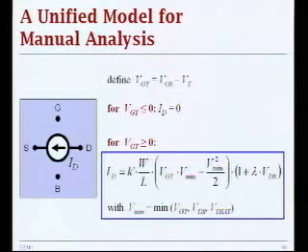People sometimes use the alpha power law model for the drain current, where instead of a quadratic relationship, you say this exponent is no longer 2, but some factor between 1 and 2, and that includes the velocity saturation effect. This is the model that we are going to use in the class for the MOS transistor.